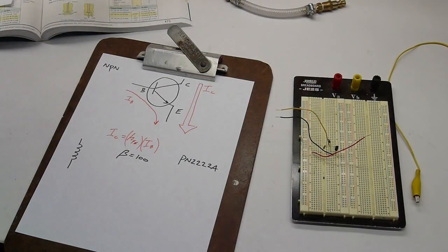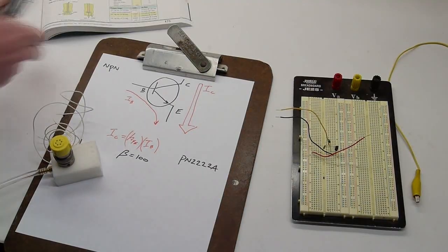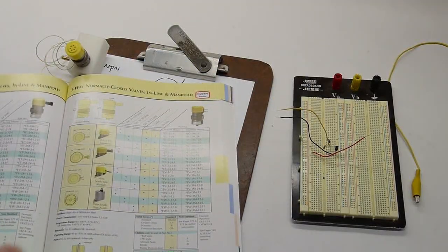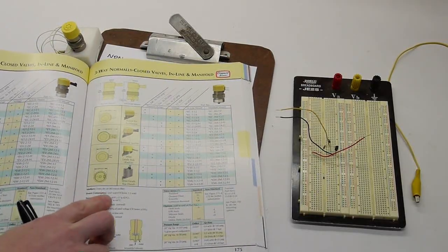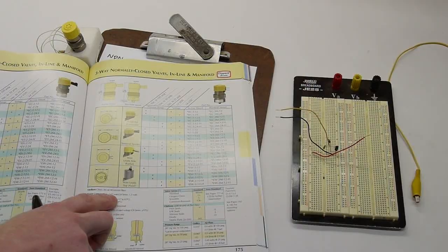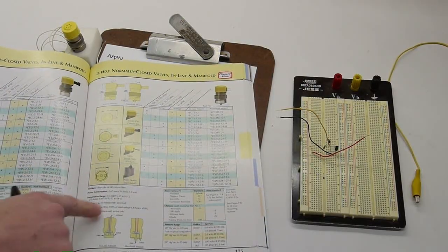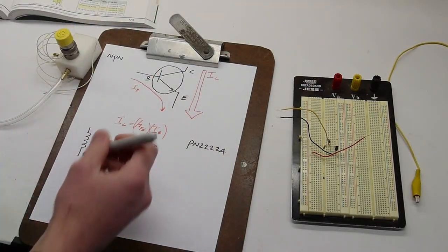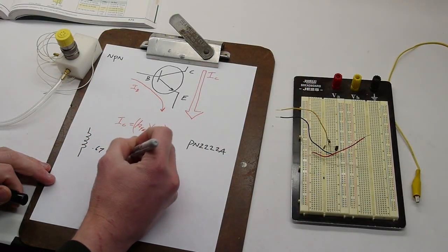So anyway, let's get back to the design that we're actually doing today, this solenoid valve. This is a clippered solenoid valve, and if we get the spec sheet in here, there's not very much for electrical specifications. It just says 0.67 watts at 12 volts. They make this in 12 or 24 volts. This is a 12 volt variant.